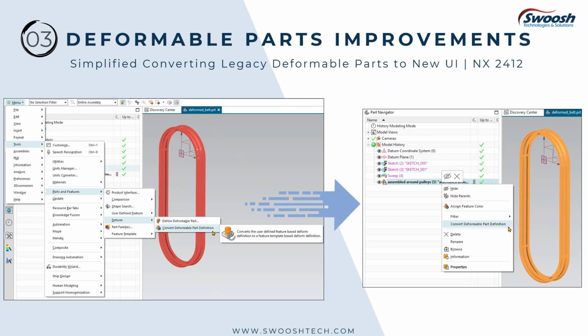With the December 2024 release of NX, we've simplified converting deformable components by bringing this action to a simple MB3 operation in the Part Navigator. This makes it so simple to bring forward your older UDFs or deformable components into the new Template Studio Author environment. You'll be able to take advantage of the new flexible and robust modernized UI and the editing capability.